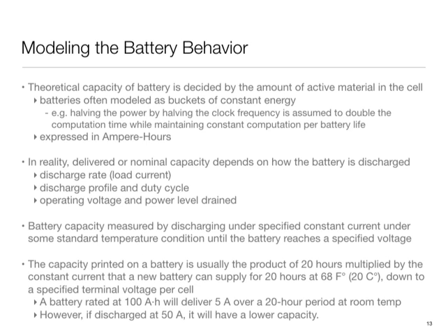So some years ago, 15 years ago, in the early days of mobile computing, this led to a search for better abstractions for this thing. It's just like saying a processor is not simply something which consumes a constant amount of power. Likewise, a battery is not something which you can think of as a constant amount of energy. So in reality, the capacity of a battery, how much it actually delivers, depends upon the current, or the power equivalently, as well as the profile.